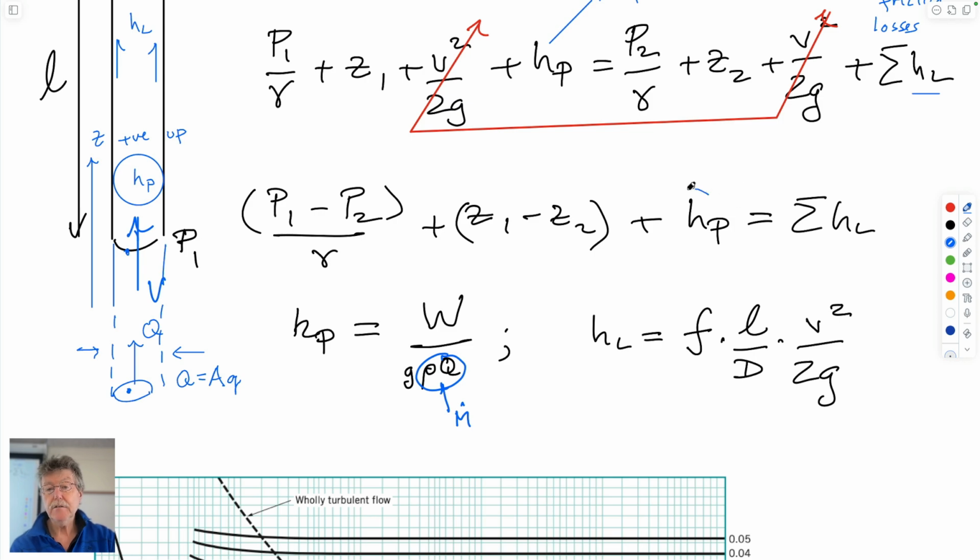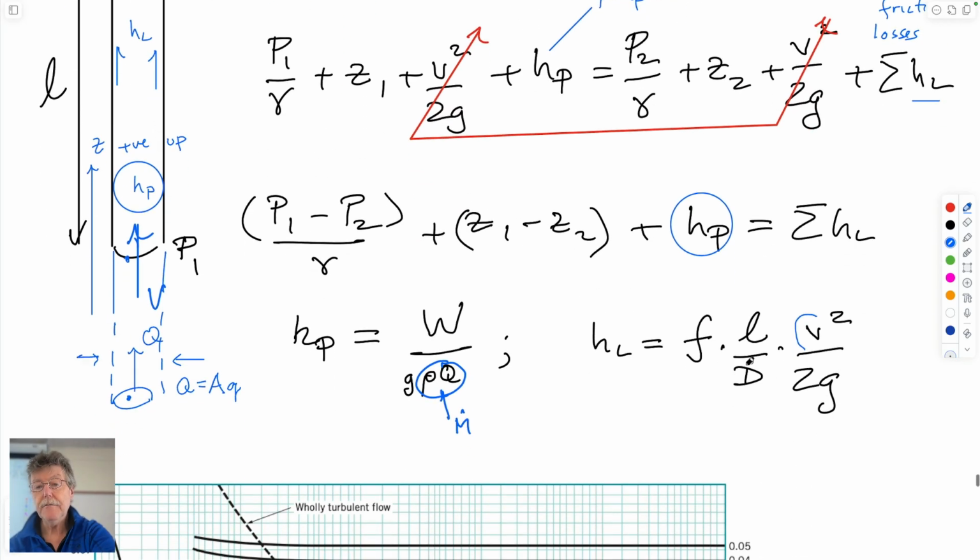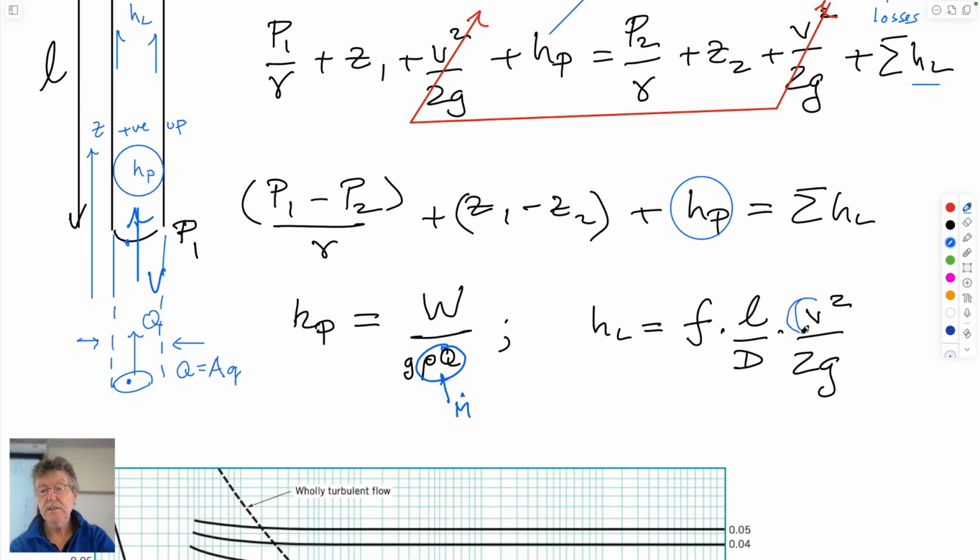And you'd want to be able to size the pump for the given magnitude of flow that you get. So you typically might choose a volumetric flow rate that you want. So if you choose the flow rate you need, then from that, for a given diameter of a pipe, you would know the velocity it needs to travel at.